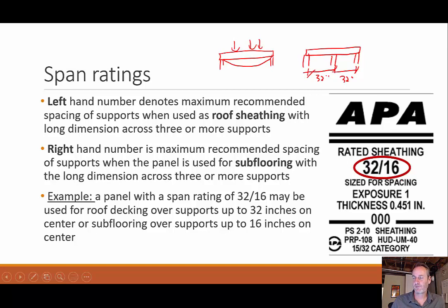One that a lot of people aren't as familiar with, but I used a lot, was 19.2 inches. That actually evenly goes into 8 feet as well, 96. And the reason that becomes such a good measurement when I was doing concrete work is because 24 was just too far of a span. Our plywood could not span a full 24 inches. And if we go down to our next one, it would be 16 inches. Well, 16 inches means I have many more members, right? Well, what if I did in between those two?